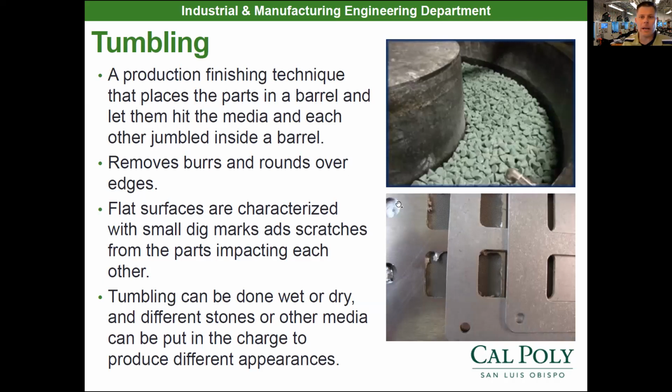A very popular one out there for machine parts is tumbling. Has anybody ever had a rock tumbler when they were a kid? You put a bunch of rocks in and they sat there and tumbled on top of each other till they got real smooth. Same thing happens with mechanical parts.